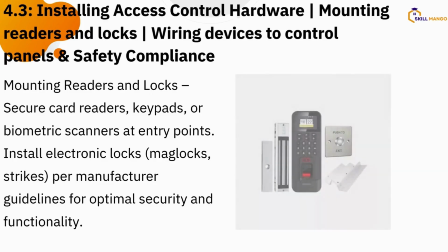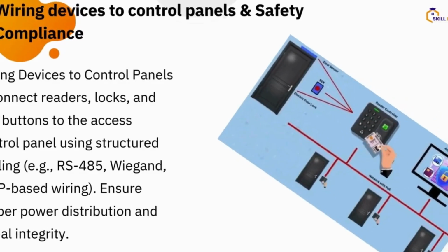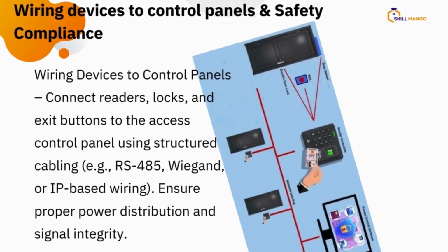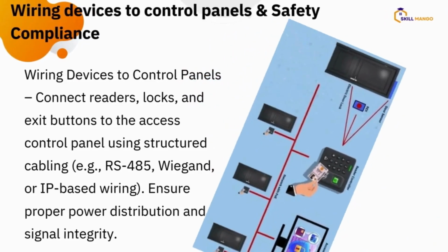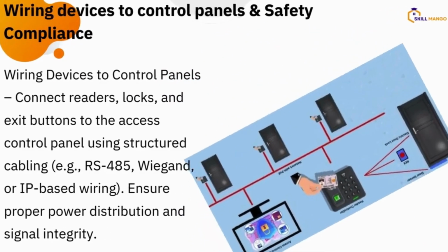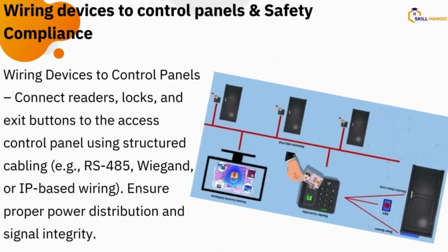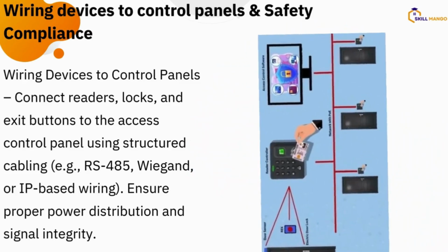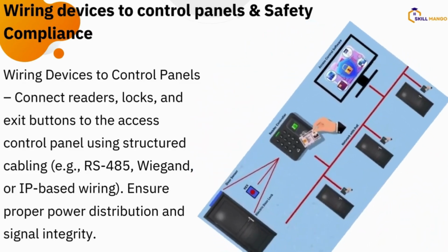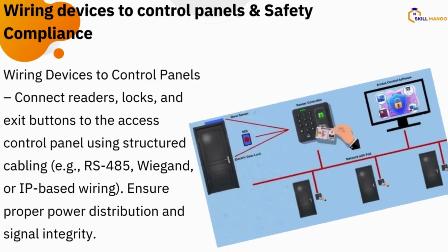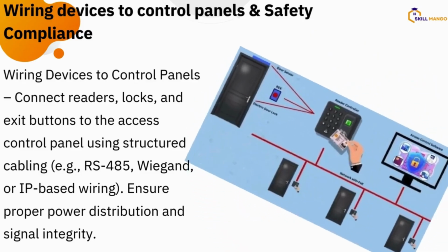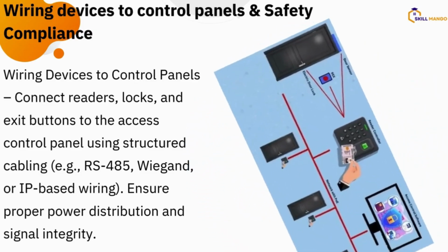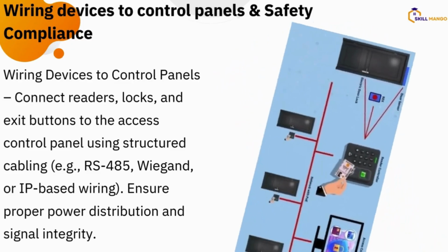All right, then you position your power supply somewhere to power the device. Okay, so all this has to be well planned and managed. Okay, so it's very, very important. If you look at this drawing, this diagram, you see that all the wires are meeting at the reader. It's very important. All the wires from the mag lock and from the exit button go to the reader. Then the reader is the one doing the authentication.